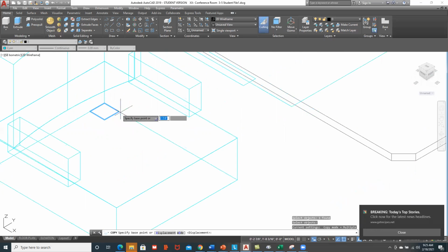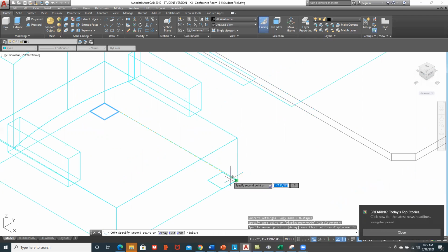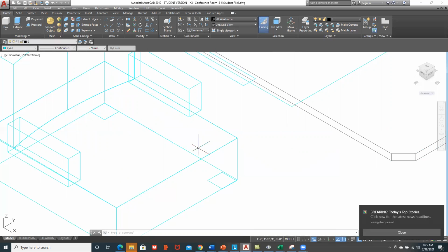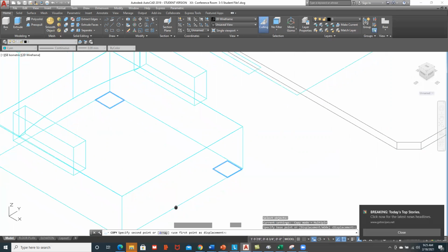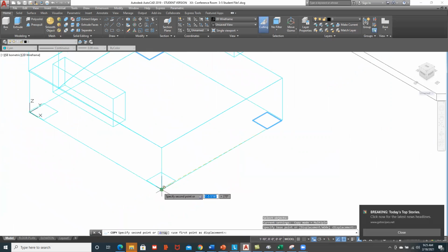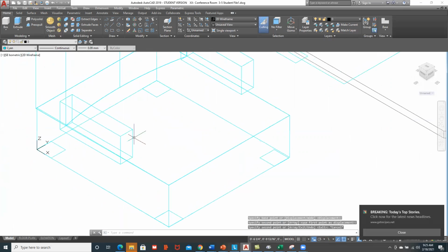As you're working with 3D objects, essentially what we're doing is moving the 2D XY plane. And then once we do that, we can start to manipulate the object into 3D. So we'll copy that. I like to use 2D snaps because I'm comfortable working in the 2D world. There I've put 4 legs for the chair on there. And you'll notice I'm using a wireframe because I want to be able to see through the object.